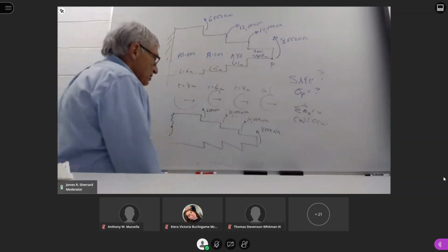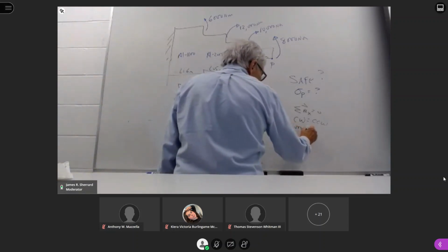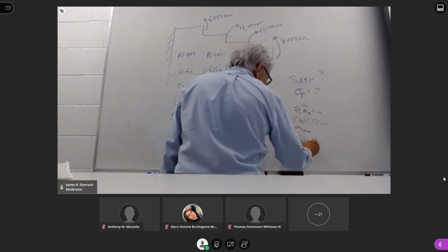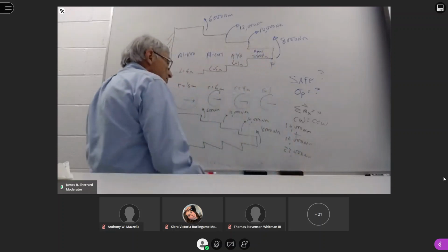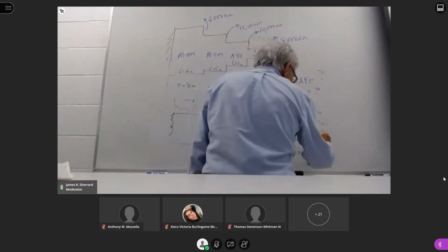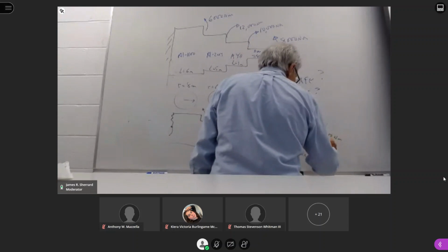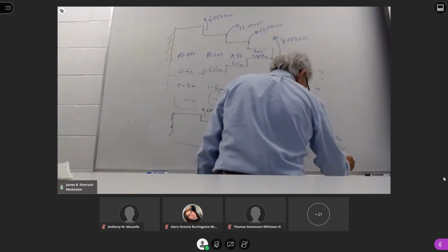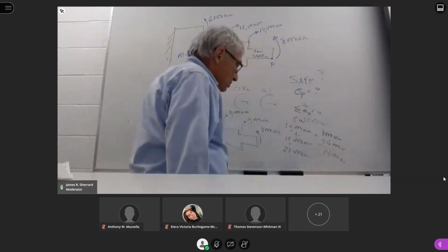If we look at the clockwises, we have this guy and this guy, for a total of 22,000 Newton meters. If we look at the counterclockwise guys, we have 8,000 and 6,000. That's a total of 14,000 Newton meters. So we know that 22,000 does not equal 14,000.